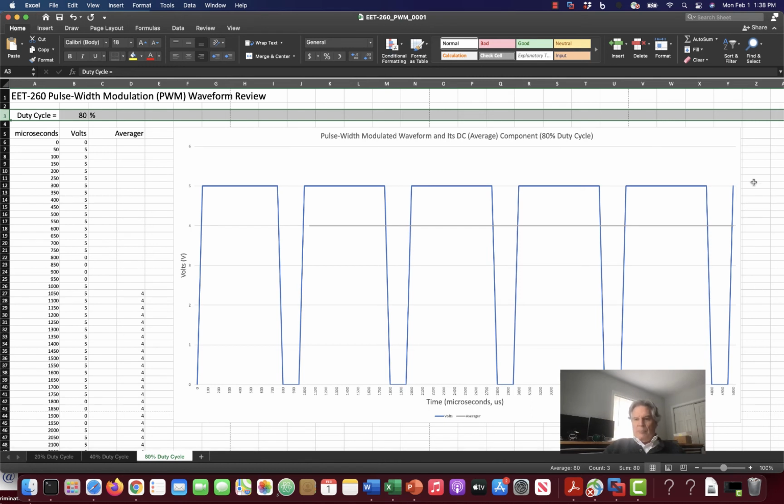So that being said, we'll get on with other kinds of motor control, but sometimes under the hood of these other motors, be they positional servo motors, continuous rotation servo motors, or brushed and brushless DC motors and all that sort of thing, this technique is most often the one used to control the brightness of some lighting, or the speed of a motor. It's also used in switching power supplies, which makes sense.